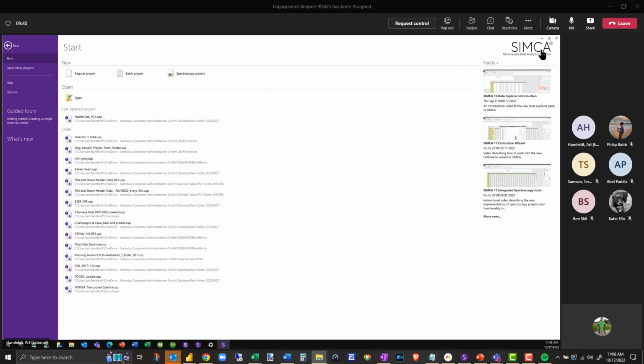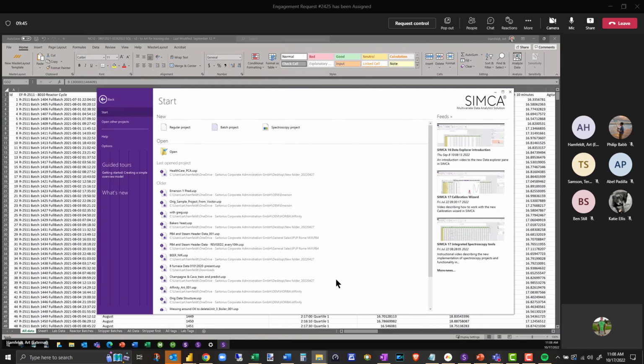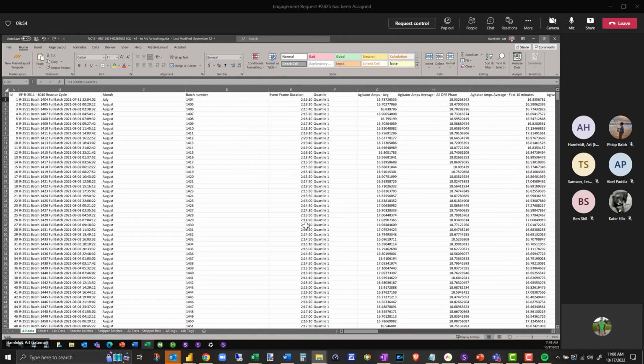It does look different. I didn't find anything in my looking at it. I looked at their TTA test, which is a quality test, and I did an OPLS with it, and pretty much everything that lined up with it is stuff that should line up. In other words, it's just confirming what we already know. The TTA lab analyzer data would be my Y variable, and then I would have the TTA coming out of the Slaker right next to it. And you're like, okay, I would expect those two to track together, right? They're confirming each other. So I had a lot of that.